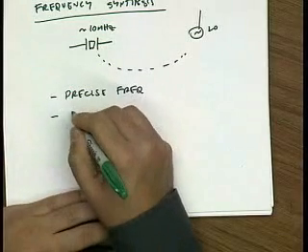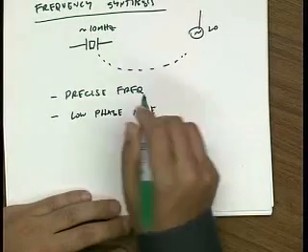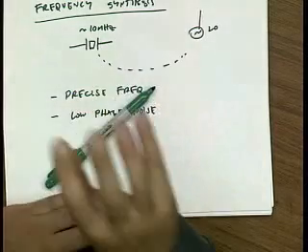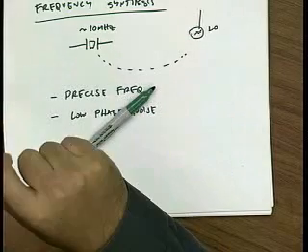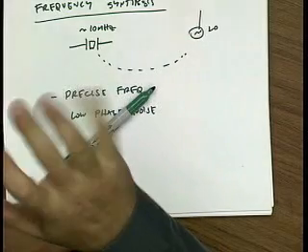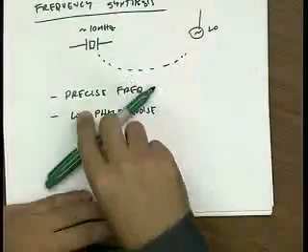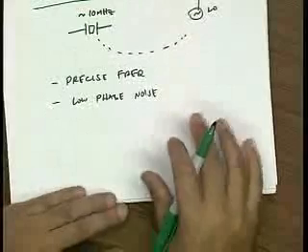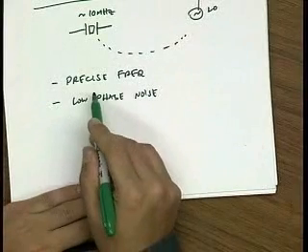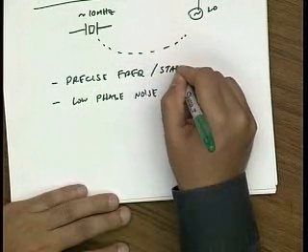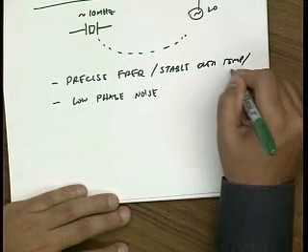You also need low phase noise, because even if you somehow, using an atomic clock, manage to get your LC tank just tuned to 1.001 gigahertz, and then you leave it alone, it's going to start moving around like crazy, right? It's not stable. So that means that basically we need it to be precise, we need it to be stable over temperature and process, let's say.